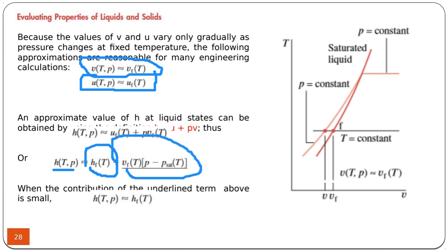However, this term is usually very small, so you can still say that the enthalpy of the subcooled liquid is almost equal to the enthalpy of the saturated liquid at the given temperature.